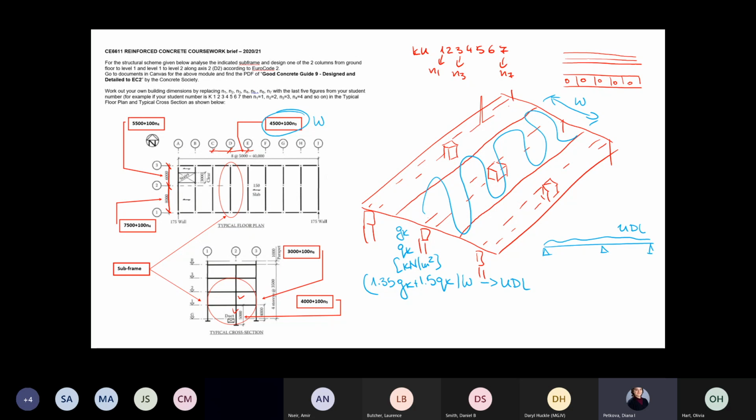Now, we're not going to worry too much about the envelopes here. We're going to put full load in the left span, full load in the right span. What we need to know is really what our diagram would look like, in terms of values. And most importantly, we will have, of course, some shearing forces as well. So technically, we need to find our reaction at this support here, which is the reaction from the analysis of the left span and the right span. So we're looking at the reaction RB. This will be our axial load for the column.